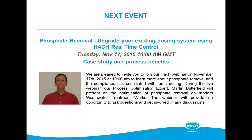Okay, and so with the minimum requirements of an inlet and an outlet ammonia monitor, maybe you could just give a little bit of an insight into a preference with regard to, say, an analyzer and a probe, because again, there's different technologies available for measuring and monitoring ammonia. Yeah, we always use wet chemistry analysis. We've found that, in the UK at least, it's by far the most robust method. There are ion selective electrodes available, and they can work well, but they need a lot of attention.